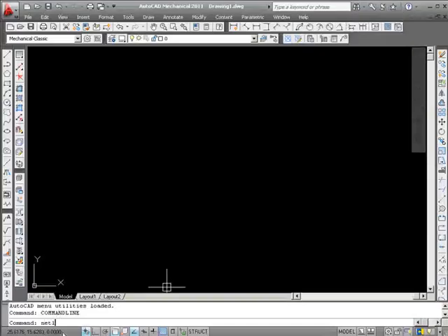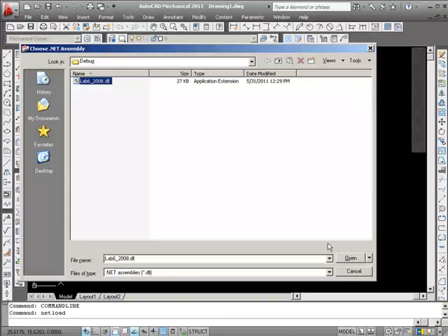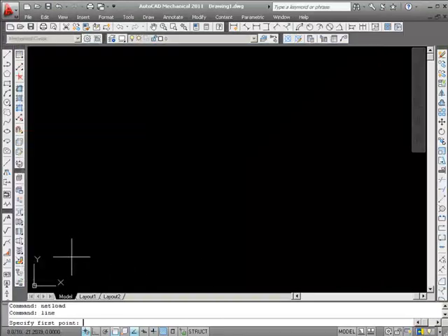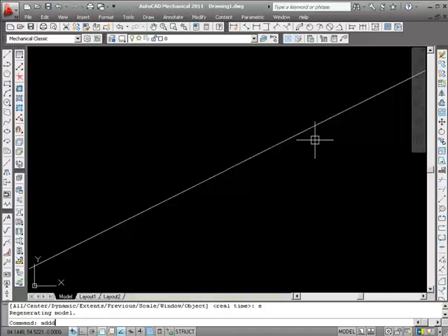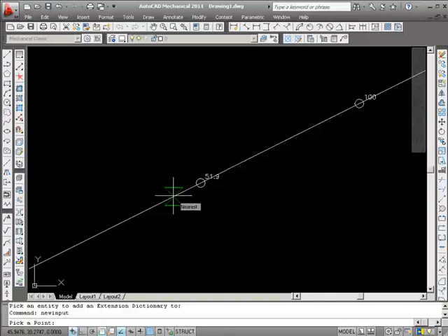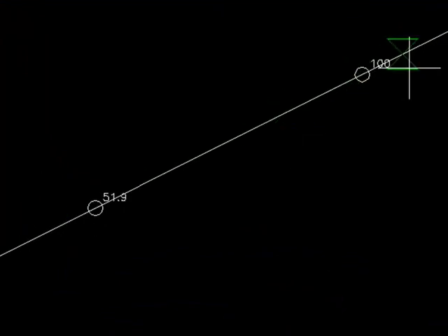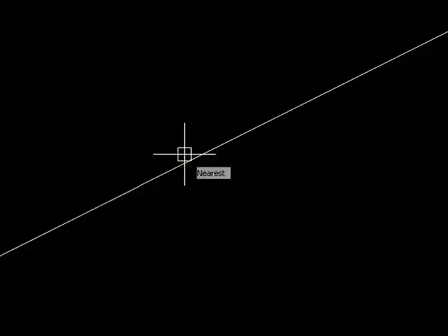Now here's AutoCAD, and let's load the DLL. Try the same steps again. The line, make it 120 units. Zoom Extents. Let's add the data. And then run new input. Hover over the line now, the data is correct. So that was a bug in my code. And now I get 51.9 and 100. So that is the temporary graphics example that this lab does.